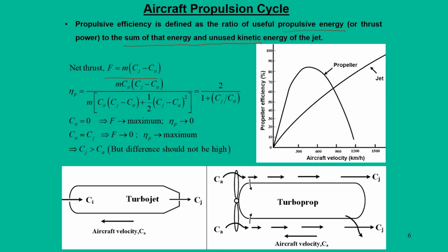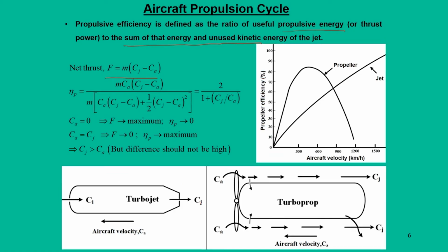So, the entry energy and leaving energy are equated by an energy balance: one part of the energy gives you the thrust, the necessary power for this thrust, and the other part, which we call the unused kinetic energy, also gives the necessary enthalpy difference between entry and exit state. That part, if you actually calculate it, we call the unused kinetic energy.